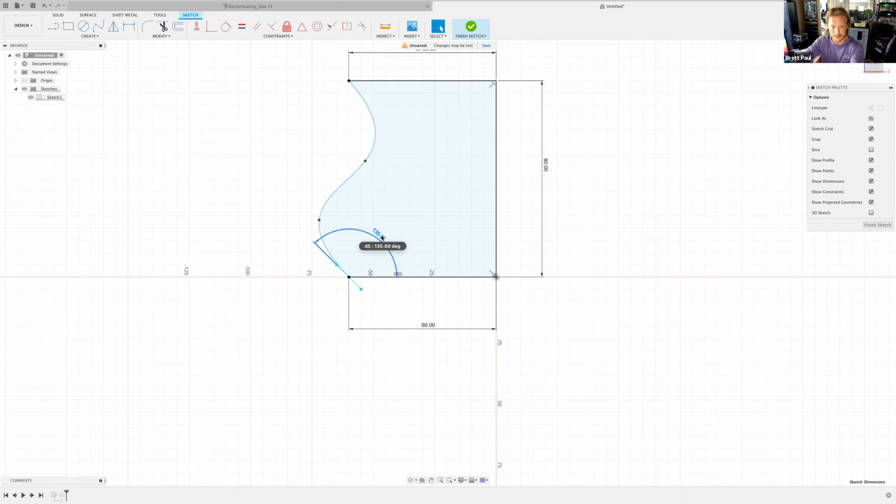Let's make this. I'm actually going to delete that, and I'm going to go like this. So see how I can... Mickey, this is kind of getting to what you were asking. It's kind of tricky, which angle do we choose? And even when we get in really close, it might even change to a magnitude as opposed to an angle. We're not in an instance where I can right click and change what dimension I'm trying to define, because the only thing I can define right here is an angle. So I'll try and find one of those where we can right click and choose an option.